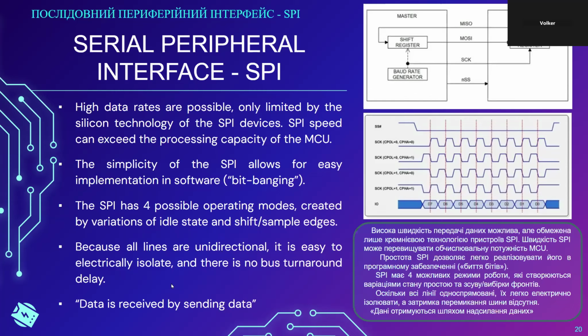But what you could do is you could move an SPI A to D converter, analog to digital converter, to the side of the 220 volt AC and connect this SPI A to D converter through optocouplers to the main microcontroller that is doing the measuring. So sometimes there are useful situations where isolating, or having the option of isolating an SPI device on the same circuit board, makes sense.